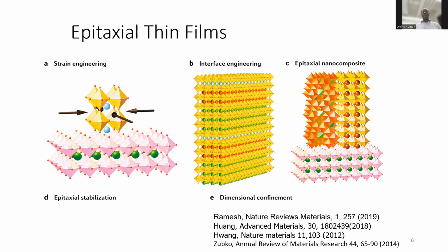Right, so if we can grow my material as a thin film, make the material very, very thin so that along one direction, it's only a few atomic layers thin, there are a couple of interesting things we can do. One of the things we can do is referred to as strain engineering, where we can take a material which has some crystal structure. So for example, if you took some of those layers of diamond or graphite, and you grew them in such a way that you could stretch them or compress them by tiny amounts. This is referred to as strain engineering.